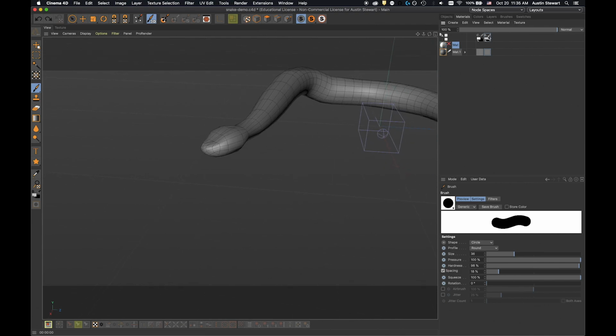We're going to turn off the paintbrush on the bump, turn the paintbrush on the color channel. And the other thing here is there's this little flip open thing. What these two little icons are, are layers. And right now, each of these channels just has one layer. It basically has a background layer. If I click on the layers option, you'll see I have this matte.1_color.tiff, and I currently have a background layer.